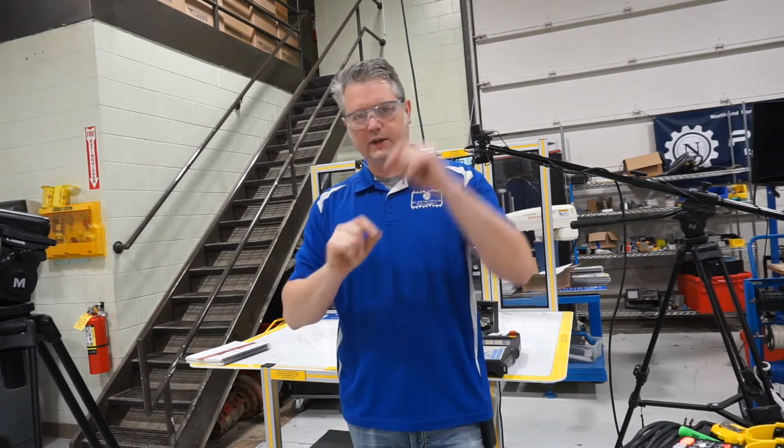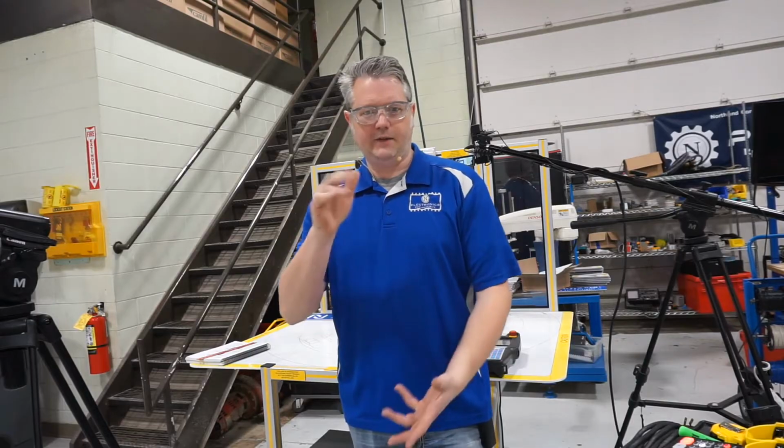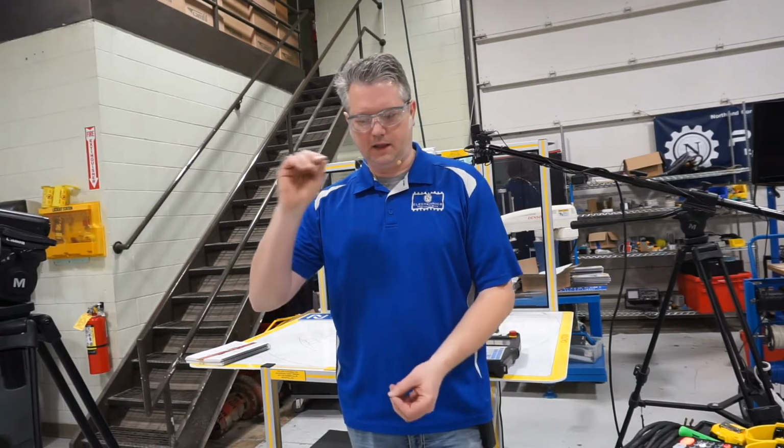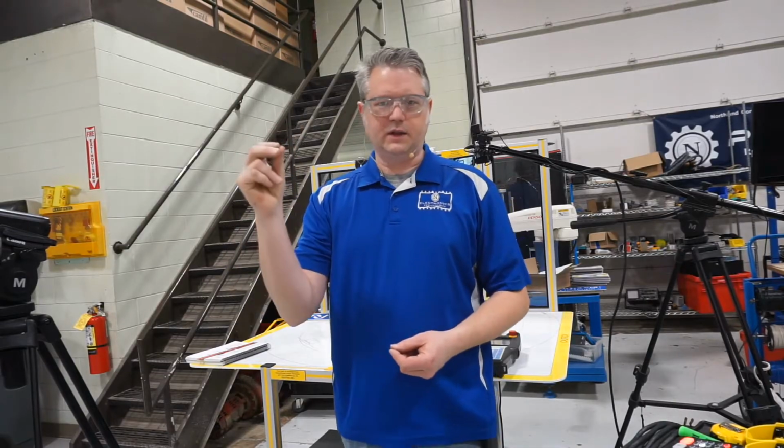It was drawn up in CAD or drafting software, and you know that the center point is at whatever location. You can use direct entry to put those numbers in, and it just makes it really simple. So those are probably the easiest ways of doing tool frames, through measurements, or by having the dimensions from the tool center point to where it mounts to the end of the tooling plate of the robot.